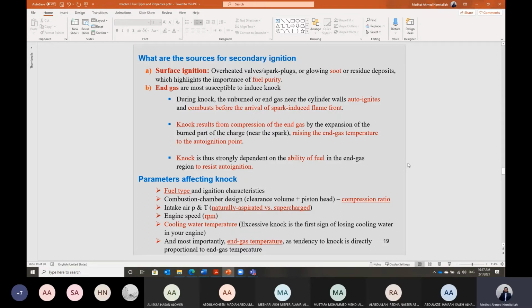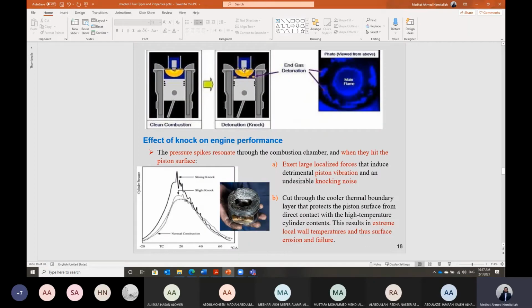It will self-ignite. But usually for a fuel like gasoline, we add some additives like alcohols, bioalcohol like methanol or ethanol, or some additives like benzol. We can add those additives to the gasoline fuel so that it will raise its self-ignition temperature. We don't need the gasoline fuel to self-ignite because we have a spark plug here. The spark plug will initiate the combustion.